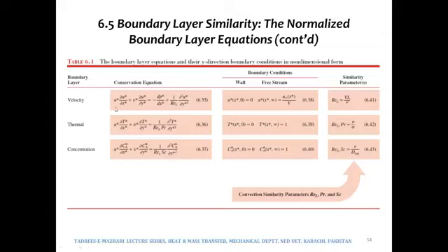So over here, if this is the differential equation and we want to find its solution, we would be integrating it, and that integral would give us the solution of u star as a function of x star, y star, dp by dx. Whether we consider dp by dx or not does not matter, because we had seen that dp by dx in x direction does not change, so it remains 0, and in terms of Reynolds number.